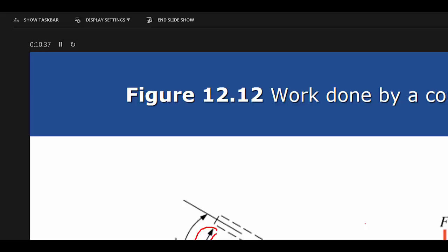We're going to set this at 540 RPM, that's our standard, but a lot of tractors can push faster than that. Just something you have to be aware of. It would be like a preset arrangement; you know what your machine's going to run at.